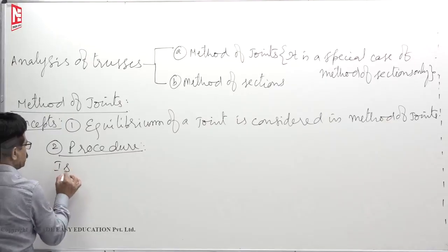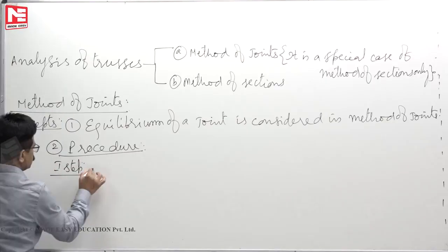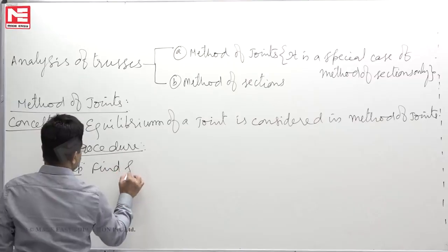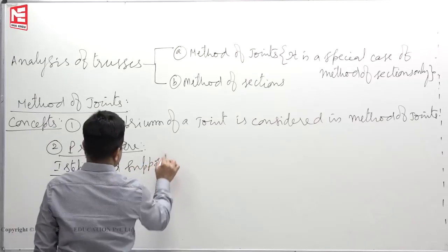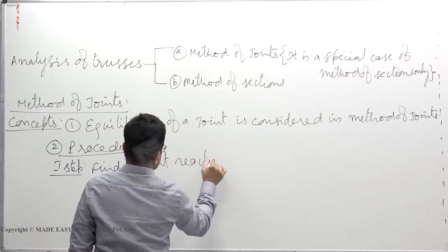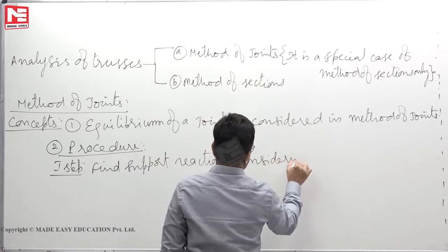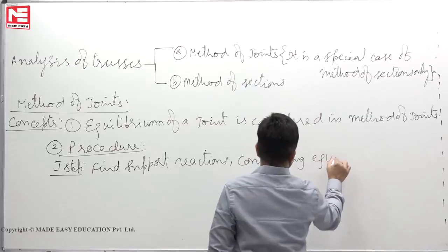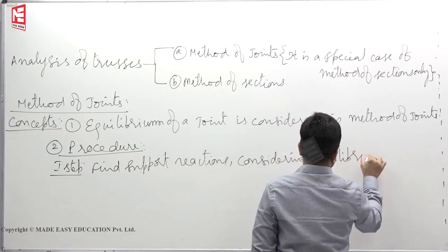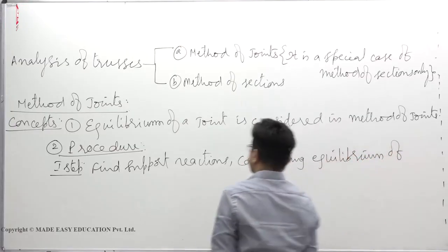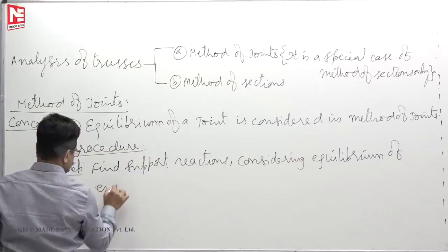So first step, find support reactions considering equilibrium of the entire structure.